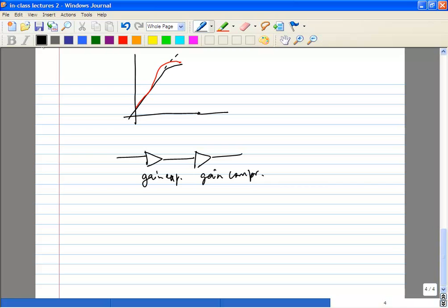But in general, we never operate the amplifiers near the 1 dB compression point, particularly in modern designs. If you take LNAs or systems like that, you probably will never operate them near the 1 dB compression point. Now the spectral regrowth could be due to phase or amplitude distortion. You may take care of amplitude, but phase would happen, for example, in a transmitter PA where you could be operating in very high compression.